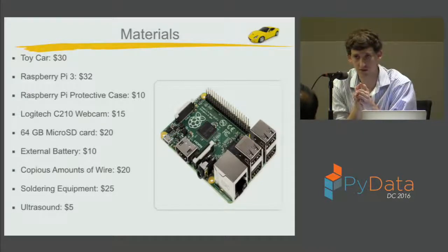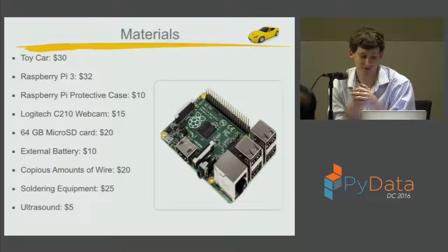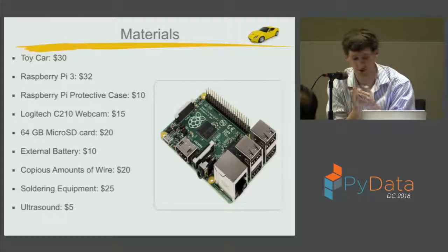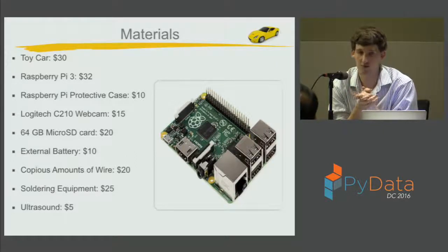The battery is really important, especially if you have a small car, because it just takes up a lot of space, but also it's really heavy. So I had to experiment with a couple of different batteries, and actually the battery that I liked most was one I got for free, and it worked best. So you don't necessarily want to go for the charge capacity, but more how much does it weigh and how well does it fit inside of your car.